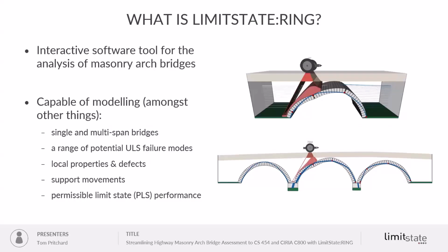What is Ring? For those of you again who don't know, it's an interactive software tool that allows us to analyze masonry arch bridges, and it's capable of modeling, amongst a lot of other things, single and multi-span bridges, a range of potential failure modes, local properties and defects, support movements, and perhaps most importantly for today's session, it will also allow you to analyze the permissible limit state performance.